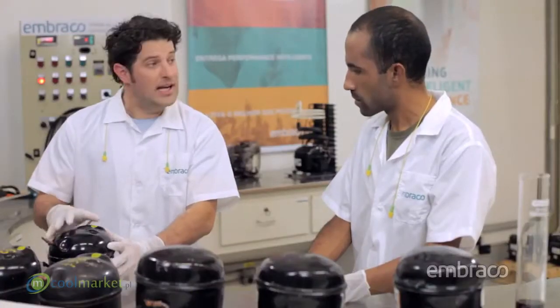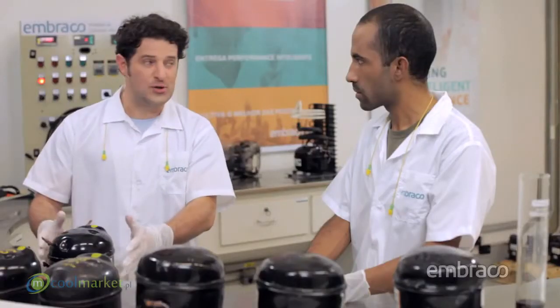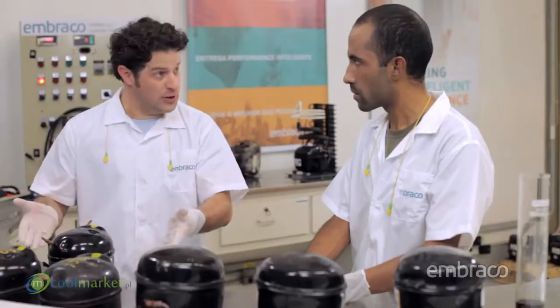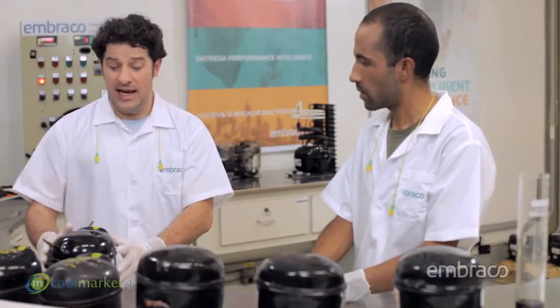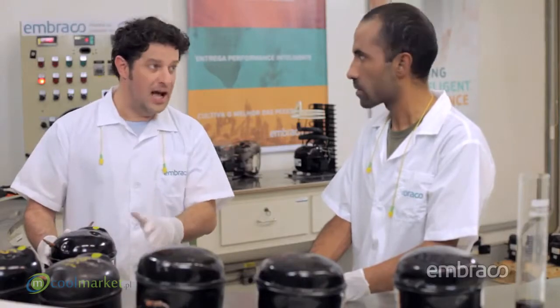What do you mean, Peter? You see, the compressor is one of the elements found in the cooling system. When a malfunction occurs in the system, often the problem is attributed to the compressor. But before you remove it, it's necessary to check the electrical wiring and the cooling circuit. Look for a dented tube or cracked insulation, dirt around the condenser in order to identify if the problem really is in the compressor. And also, before removing the compressor, we must check the electrical components.